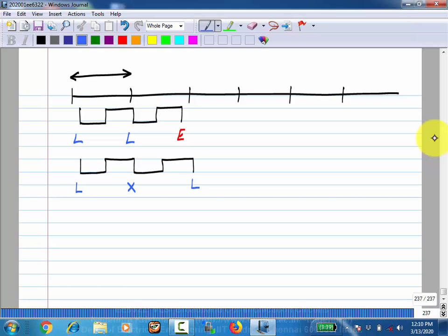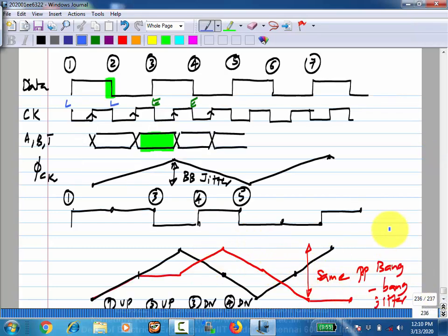So that's why, you imagine the way the clock and data recovery with the VCO works: when you have plus ICPR, it is speeding up the VCO. If you have minus ICPR, it is slowing down the VCO. It speeds up the VCO to move edges to the left. It slows down the VCO to move the edges to the right. Okay? Is this fine? So that is about bang jitter with random data. The calculation is the same, but you just have to imagine all these things to convince yourselves that the peak to peak jitter remains the same. Okay?